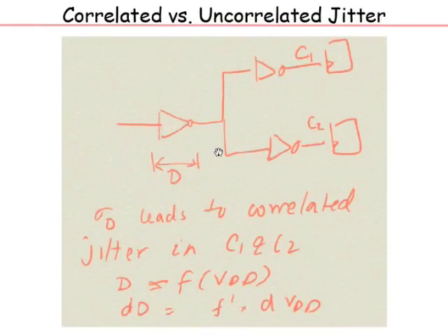So what I'm saying is, if I look at the arrival time of the clocks at these nodes, if I just observe any particular node, and if I had a way of measuring the jitter of that node with respect to an ideal clock edge, I'll see some amount of jitter. Similarly, in another node, I'll see some amount of jitter. Now, one conservative approach is to say, if both these are uncorrelated, then the total jitter which I will use is not a summation but an RMS summation. RMS summation of the two will give me the effective jitter between these two nodes, and I'm going to use that.